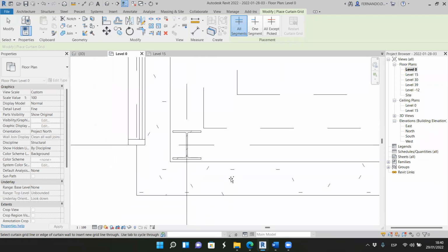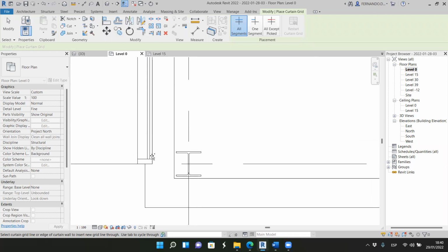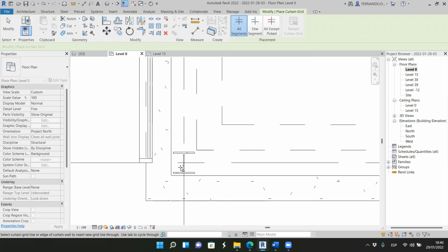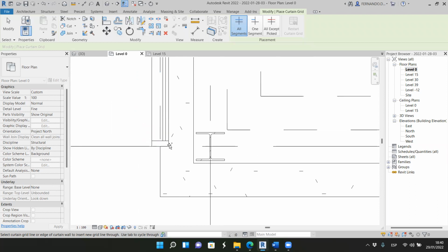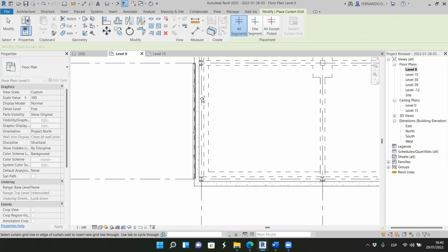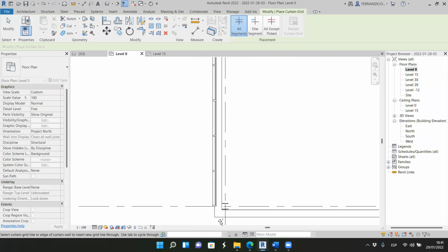Okay, so finally we will have to design the corner. We will do that later, but make sure that the curtain wall is covering this so that the thermal envelope is the curtain wall. It's not the steel structure. Okay, because steel doesn't have any thermal insulation at all, and it will be a thermal breach. So now we do this. We keep the curtain wall as the thermal envelope, and the steel structure is inside. Okay, and then we will design something for the corner.